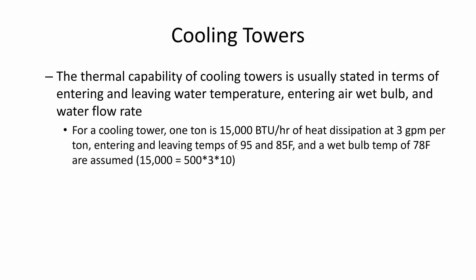So the big thing with cooling towers, the whole point of them is that they're supposed to be able to cool down your condenser water that's coming from your chiller. So remember that the chiller inside of our building is going to be creating chilled water for the building, and the evaporator barrel, we're chilling that chilled water loop for our building, and then that heat's getting rejected to the refrigerant. It's going through the compressor, and then it's going over to the condenser barrel.